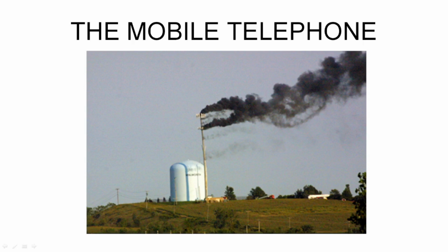And it was interesting. I worked at Harris when we were setting up a developmental cellular system in Rochester, to watch the watt meter going to the antenna as you turned on multiple channel transmitters, each one was 50 watts. So you'd see the watt meter go up to 50, 100, 150, 200, 250, 300, etc. So that's actually what happened: eventually the amount of power going through the damaged coax actually lit them off. Or, well, at least no flames, I guess, but a lot of smoke.